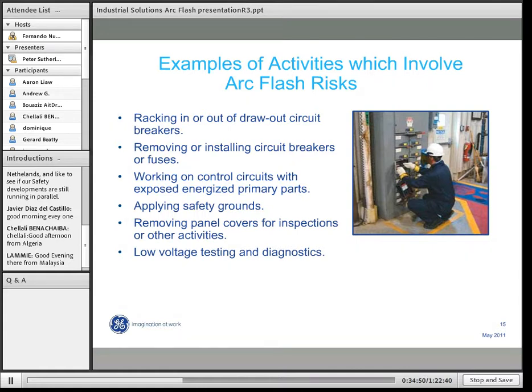You should not change the fuse on a live circuit. And I know in the past, many people, including myself, have racked out circuit breakers and have replaced fuses in live circuits, and that is not encouraged anymore. In fact, this is something that is extremely dangerous.